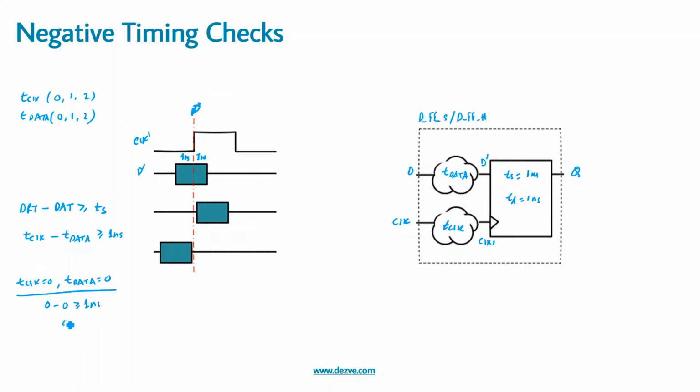So 0 greater than or equal to 1 ns. We are off by 1 ns, and that 1 ns was the setup requirement which we have not met. So this particular circuit will violate by 1 ns. If we make this dotted flip-flop with just a wire connection, without any combinational delay or clock or data path skew, it will behave exactly like the previous circuit with a setup requirement of 1 ns. Got it?